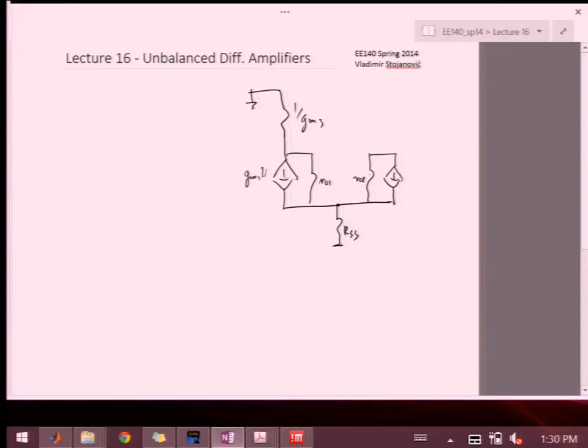RO2, VGS1. And in this case, since the gates are going to be grounded, because I'm looking at the output impedance, I'm doing a V test here and looking at I test. Let me just mark this so that it's a little bit clearer where the I down and I up is coming from.